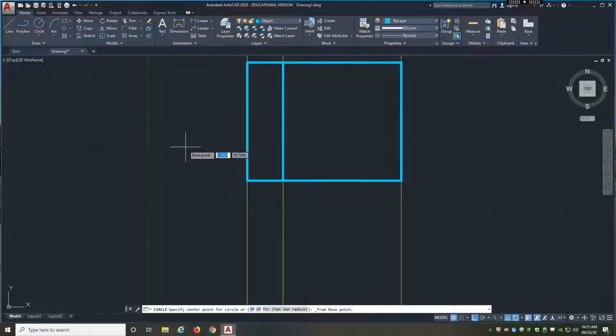You can also draw a scaffolding line, basically just a line that is 3/4 in, 3/4 up. That'll give you your point as well. But using the snap from, I need a base point. So I'm going to left click, and now my offset. I have to make sure that it is relative, and I'm going to say 0.750, tab over, 0.750, and hit enter, and now I can draw my hole right away. And again, the holes are a diameter, so D, enter, 0.250. There we go.